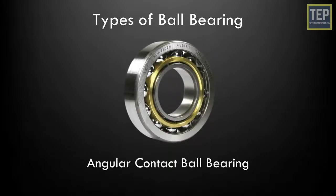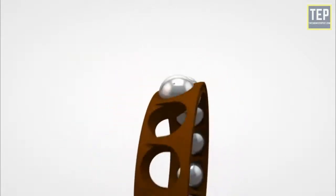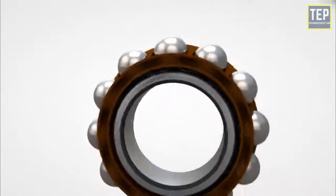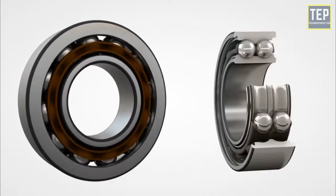Angular contact ball bearings. In this ball bearing, the inner and outer races are displaced with respect to each other along the bearing axis. This type is designed to handle greater amounts of axial loads in both directions, in addition to radial loads.